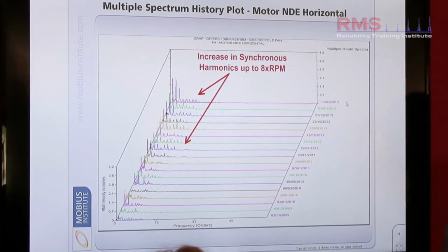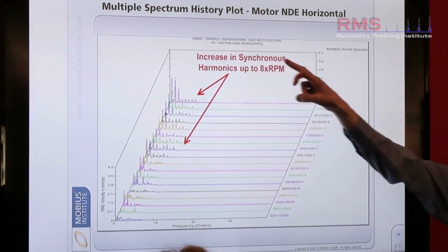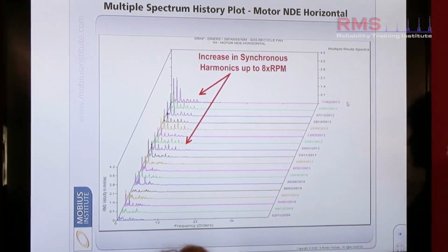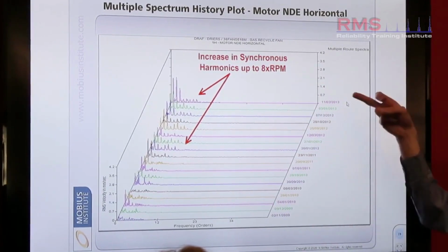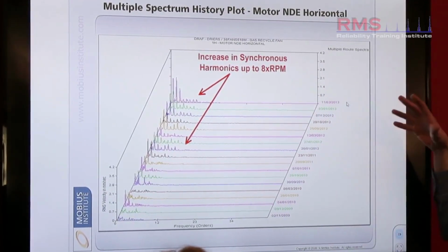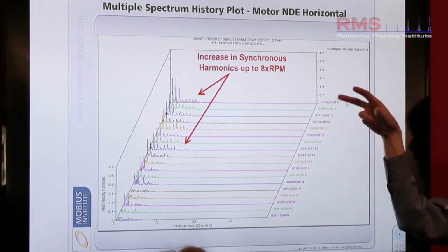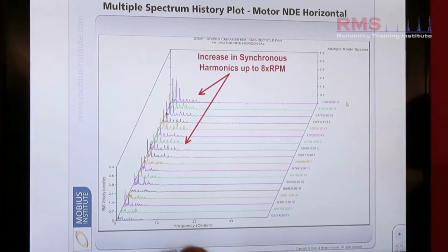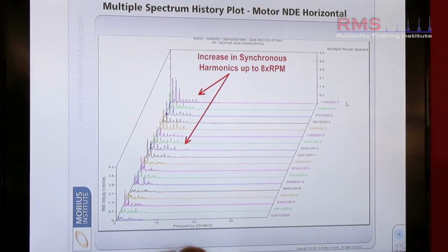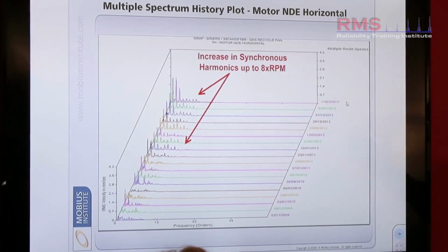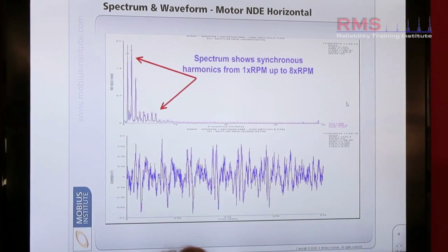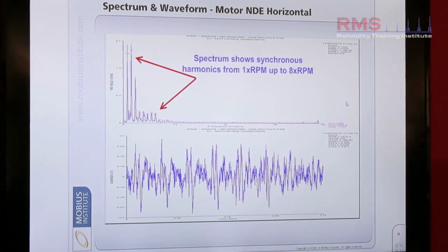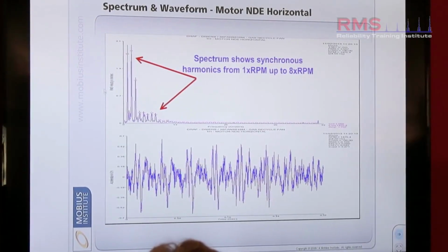This is one particular point. Again, this is on the motor non-drive end. So this particular measurement was taken at the non-drive end. The most recent reading taken at the time this was a problem is at the back. And you can see the visual picture there has changed where you see obviously more activity at the back, harmonics. So there they are in a bit more detail. We've zoomed in there if you like and just taken that one spectrum out.